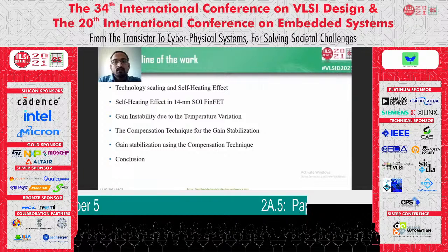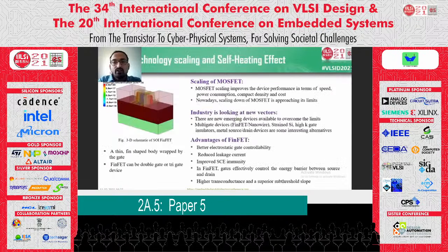Since technology scaling improves device performance in terms of speed, power consumption, cost, etc., there are, however, several challenges such as short-channel effects which also come with the scaling. So there are several techniques to overcome these limits. Multi-gate devices, strained silicon, and high-K insulators are some interesting alternatives, and FinFET is one of them.